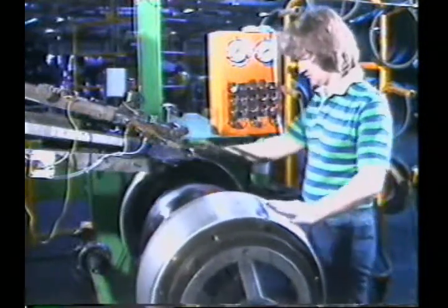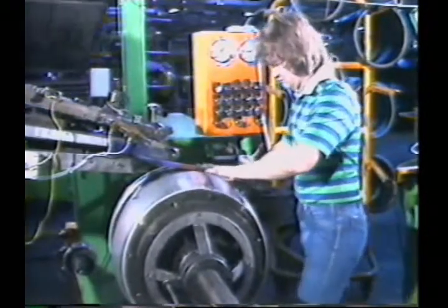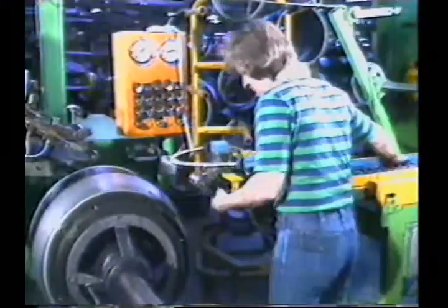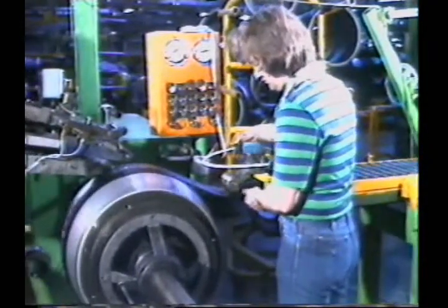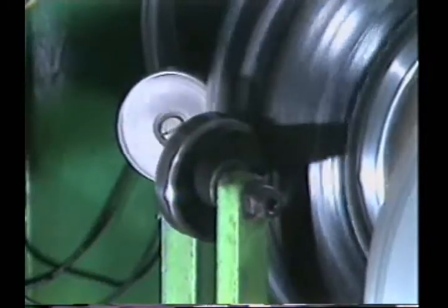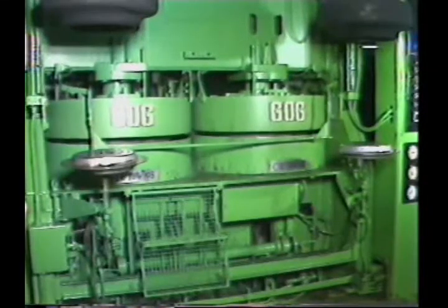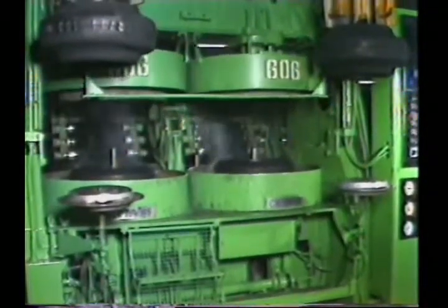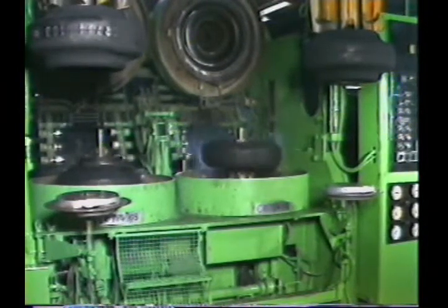At the second stage building machine, the tyre is shaped. Belts of steel wire are guided into place. The tread is then positioned, and the uncured tyre is consolidated by rollers before it is placed in the mould. During the moulding and curing stage, the tyre is subjected to high temperature and pressure, and it takes on its final fixed identity with its own distinctive tread pattern.